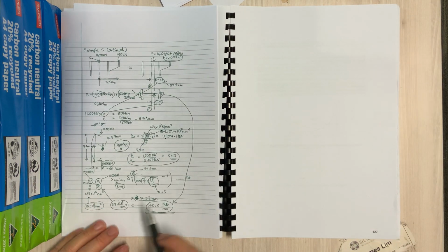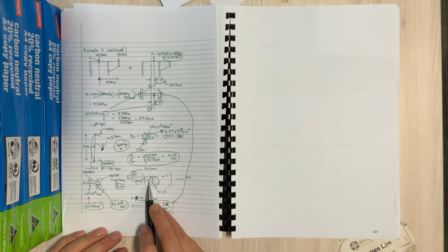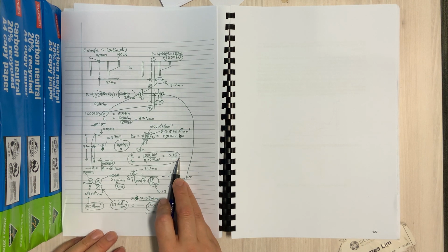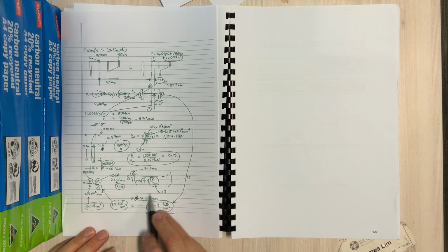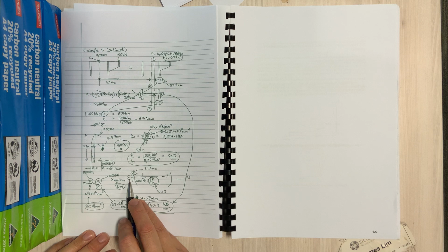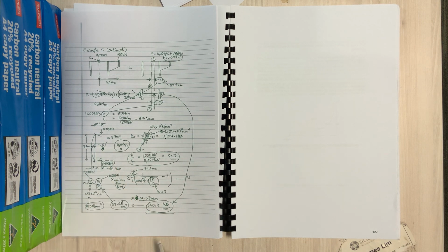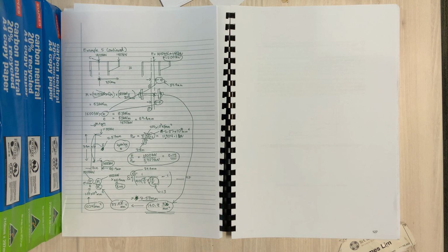So right here you can see that we've got 1 over cosine of pi by 2 multiplied by 0.13, or the square root of that, which we calculated there, and that's going to be -1. And then from all that, once we've got our deflection, which is there, plus the eccentricity, because that's the distance away from it, you can go back to your moments.